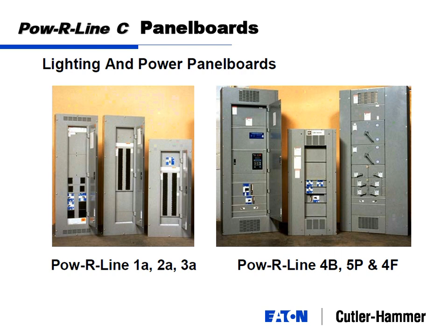So really there's two classifications when I'm thinking about a panel board. There's a lighting panel board, and I'll even further that one into lighting and receptacle or lighting and appliance panel board. And there's a power panel board. In an electrical distribution system, into your facility is going to be a main switchboard. It could be a 1200 amp service, 3000 amp service, 4000 amp service.